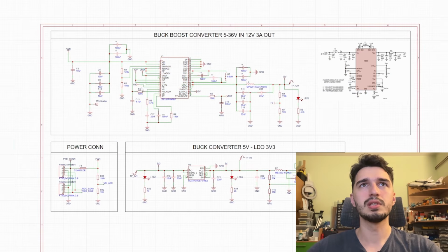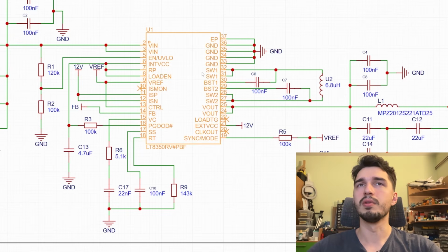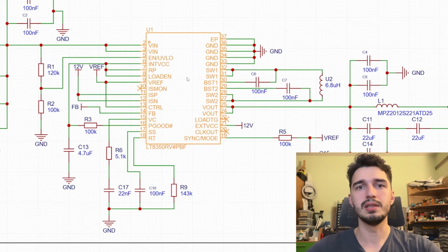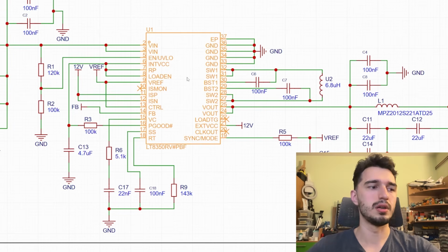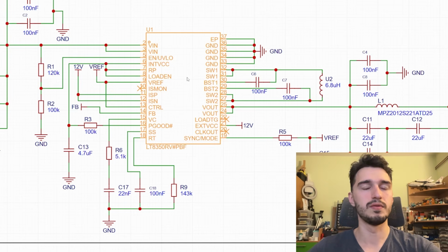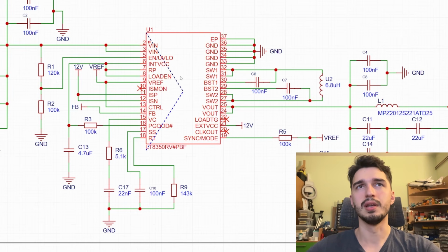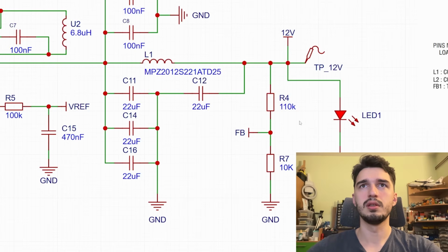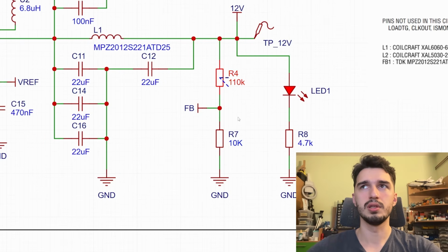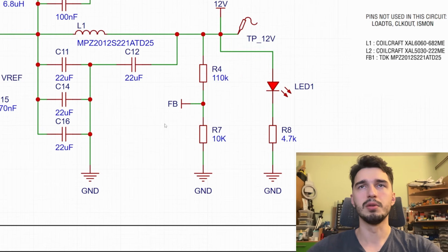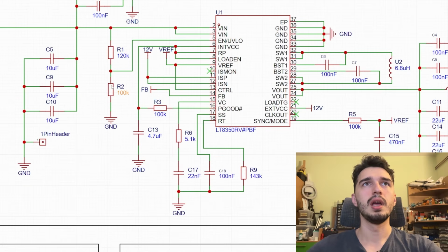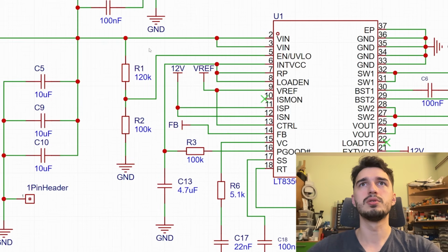On the power electronics side, as I've mentioned previously, we will need something like this. So this is a buck boost converter. The motor driver IC needs 12 volts and we need to provide those 12 volts whether our input voltage is 4 volts or it's 40 volts. And this is where this thing comes in. You just adjust the output voltage using these 2 resistors. There is a simple calculation from the datasheet, and you can set at what voltage it starts working using the under voltage lockout using these resistors here.